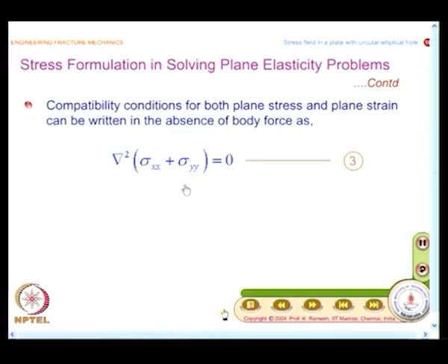The observation is very important, because I have been saying I am going to illustrate many phenomena in fracture mechanics by looking at results from photoelasticity. People have done crack propagation studies in photoelasticity. People also have done static experiments on mode 1, mode 2 and mode 3. As long as the problem is plane stress or plane strain, the elastic constants do not play a role. So, whatever I see in a plastic is same as what I would see in a metallic specimen.